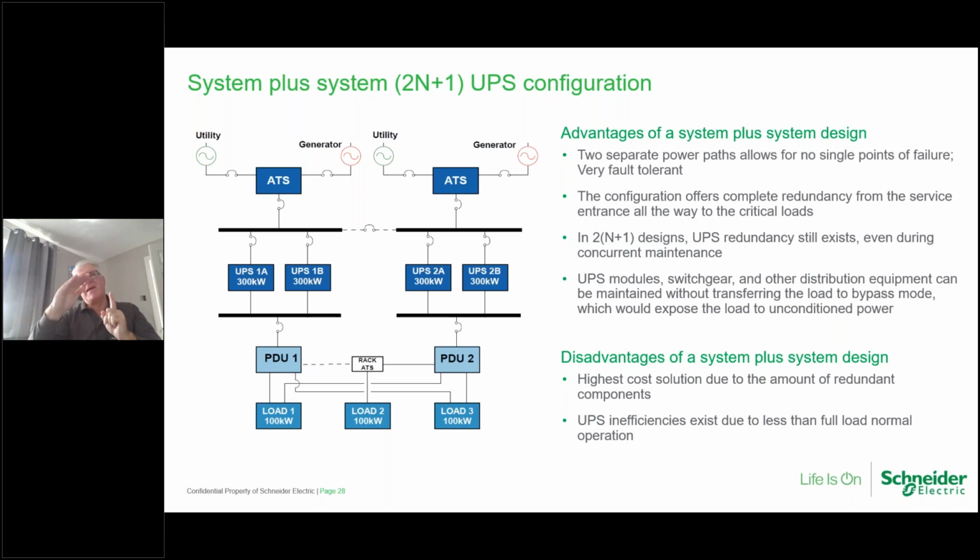It's at its highest perhaps at 75%, 50%, because we always know in our design of UPSs, rarely are they used sitting at 100%. Optimally, it could be around that middle mark, and the UPS meets its peak in efficiency and performance at that middle loading.